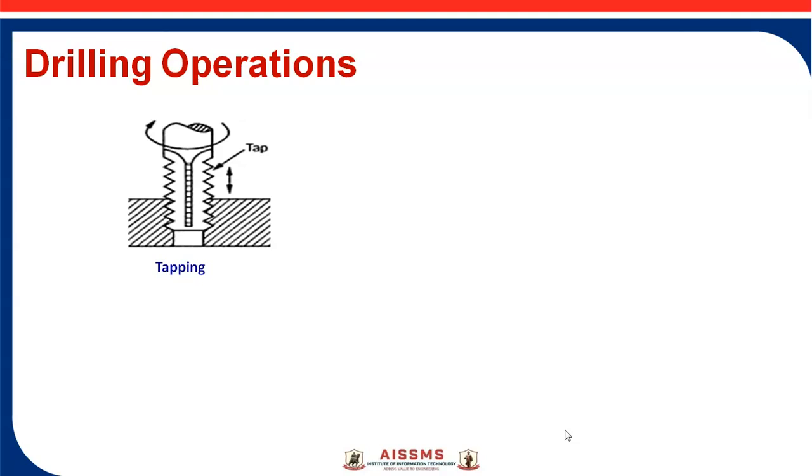Then another operation is tapping. Tapping is the process of making an internal thread in a drilled hole, and the tool used for the tapping operation is a tap. There are two parts to the operation: one is clockwise rotation of the tool, and the other is removing the tap by anti-clockwise rotation. The spindle is rotated in both directions only in one operation, tapping. Tapping makes an internal thread inside the surface.